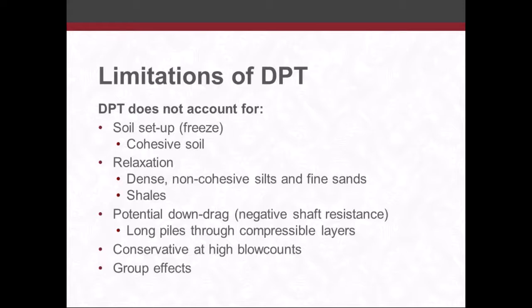For piles, particularly long piles through compressible layers, we don't evaluate the down drag or negative shaft resistance. That's something that needs to be evaluated by the designer.